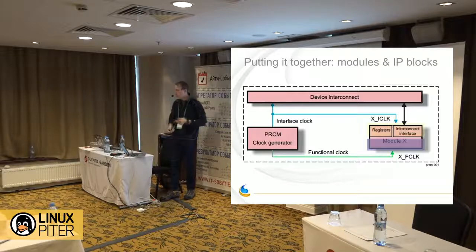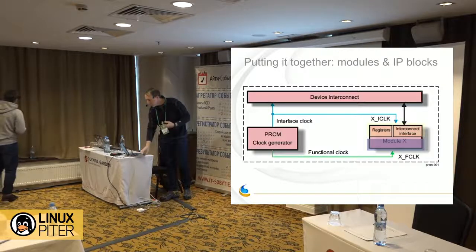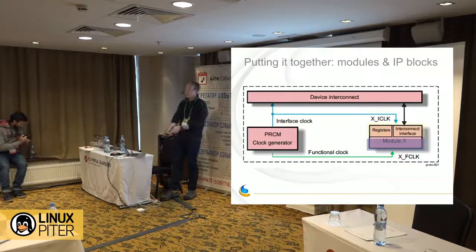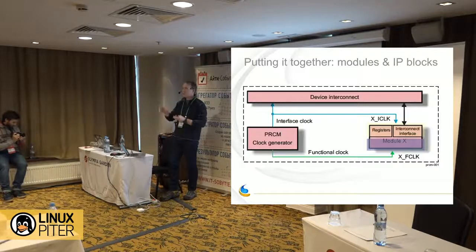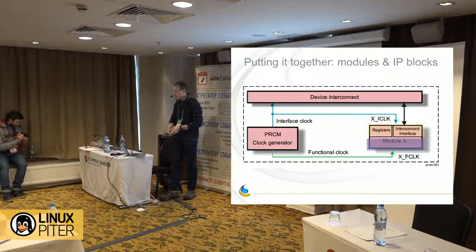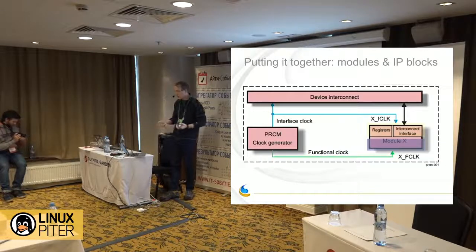Modern SoCs, I mentioned before, are filled with modules or IP blocks. These can be a variety of different things: crypto accelerator, CPU, whatever. The thing that makes SoCs very interesting to work on for me is that I'm a fan of computer hardware architecture, and SoCs are all very different. They're super messy. A bunch of different IP blocks are glued together. They have clock trees. They have power supplies. There's a DMA between devices. You have a variety of interconnects, shared memory, interrupts, mailbox schemes, and every vendor does it differently. There's not a standard way to wire up a platform, and so that keeps things interesting.